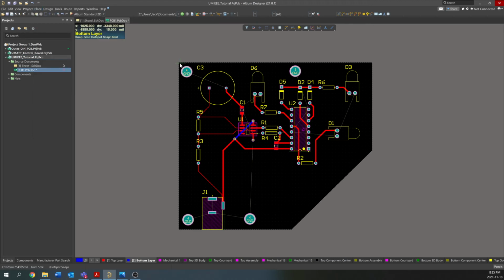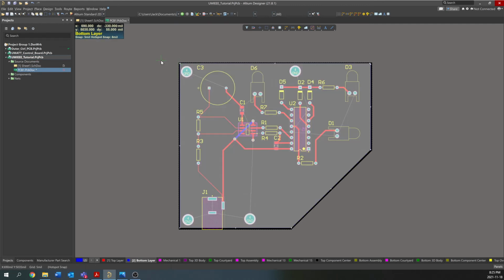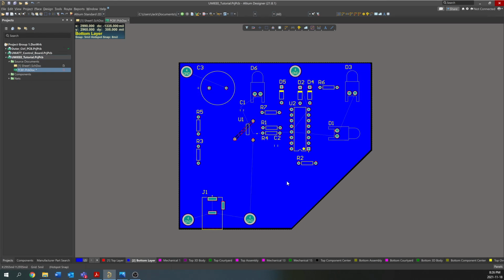Things get really complicated if you're just using 2 layers, and it becomes really nice, simple, and easy when we use a 4-layer board, and that's completely right. Just going to lay out trace like that, and then I'll have to go back up to the top here. And right click when you're done, and right click again to go out of it, and now there we go. Now we're on the bottom layer, and that's our polygon pour.